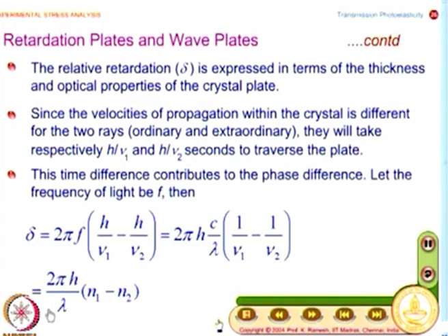So, we would confine our attention; our mathematics will become a lot simpler if I use a monochromatic light source and do my photoelastic analysis. Now, you also have achromatic quarter wave plates, where the plate gives a phase difference of pi by 2 for a range of wavelengths. You have such plates available. When there is a problem, you have an opportunity for research, and researchers develop a way to overcome this. So, that goes on parallelly.